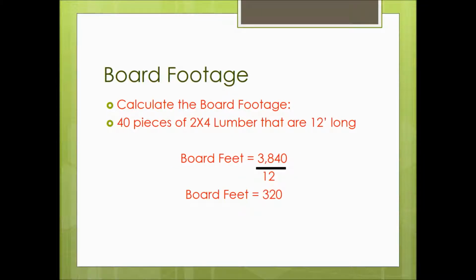We end up with 3,840 divided by 12, and there's 320 board feet in 40 pieces of 2x4s 12 feet long.